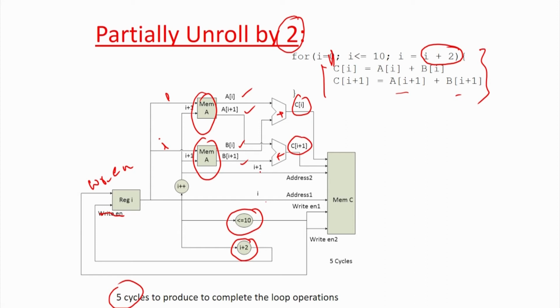If you want your design to execute very fast, then unroll is probably better, because resource does not matter. But if you are bothered about the resource, and you want to use as few resources as possible, then you should totally pipeline, so that you generate the minimum number of resources.